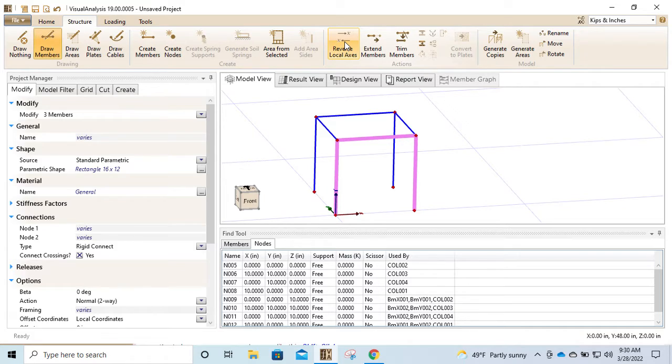Whether this beam, the axis is this way versus axis going this way, right? It becomes a real big thing if we had multiple beams in a row, right? We might have an axis that runs one way and then an axis runs the other way. You might want to report those in a series, and you're going to say, holy shit, the force flips direction. Well, why does it do that? Well, it's because our coordinates changed, right? So based on how you draw the direction.